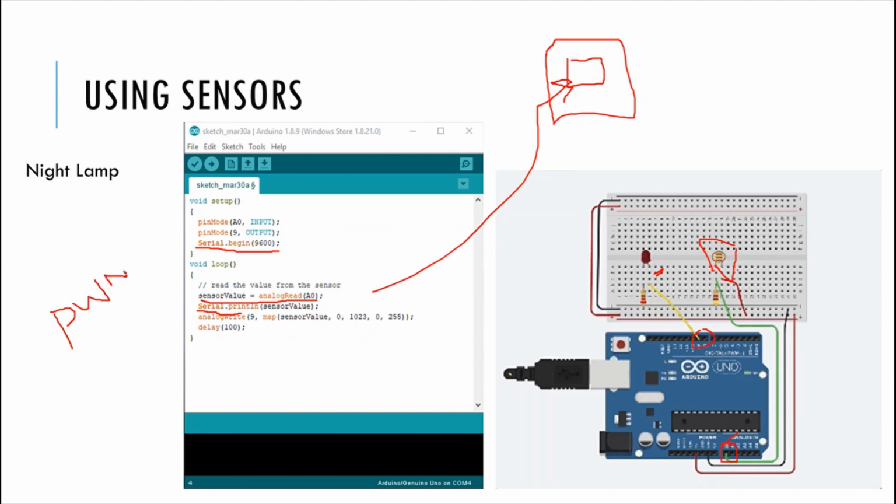Now what this does is it mimics an analog output. So instead of having a signal that's 5 volts all the way along, it has 5 volts half the time, and 0 the other half, making it look like an average of 2.5 volts. So that mimicking we will come to in further, more advanced videos, but that is the basic idea.